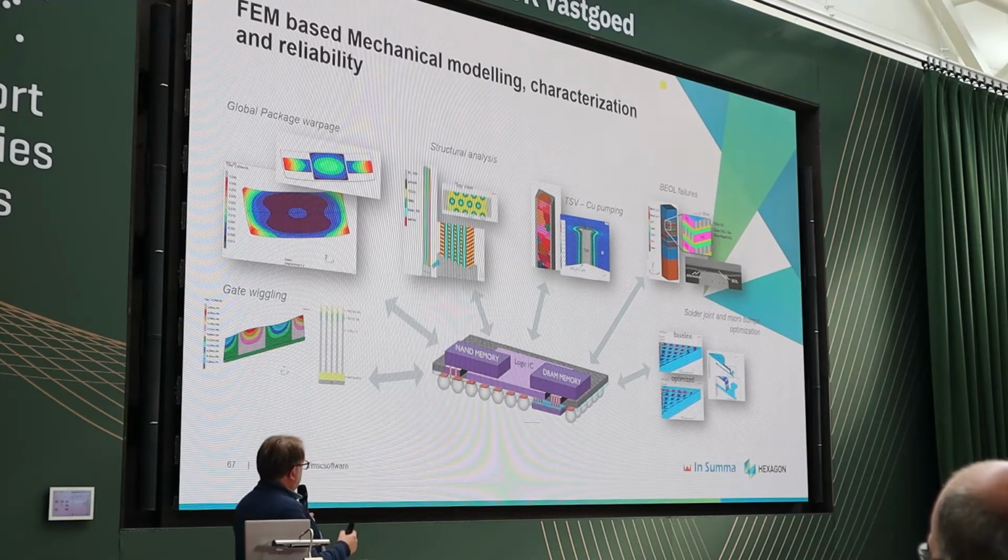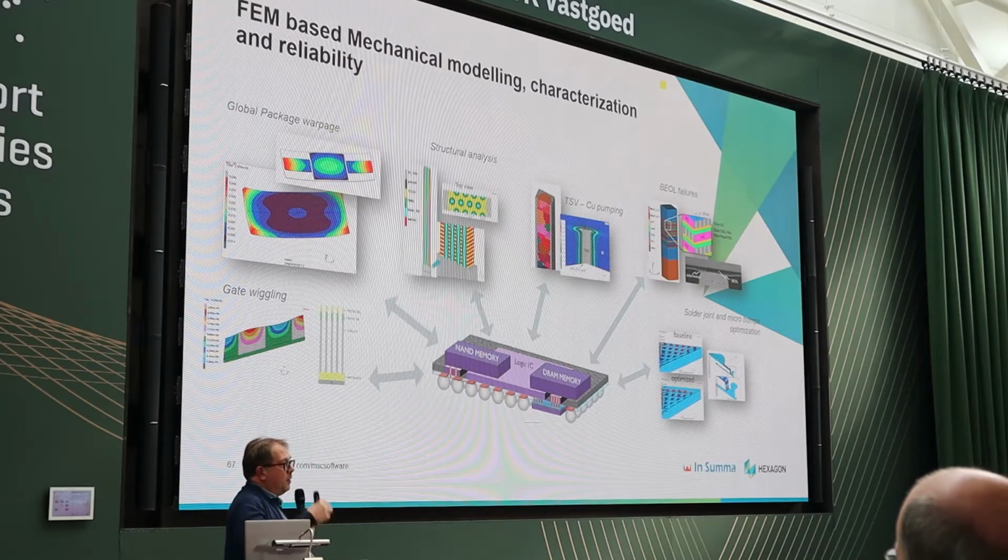Also, in order to have connections from top to bottom, they make holes inside the silicon and fill them with copper. But the thermal expansion is also a large issue, because the copper expands much more than the silicon, and you can have things like fatigue or damage to the surroundings, or even changes in the neighboring transistors because of mechanical stress.